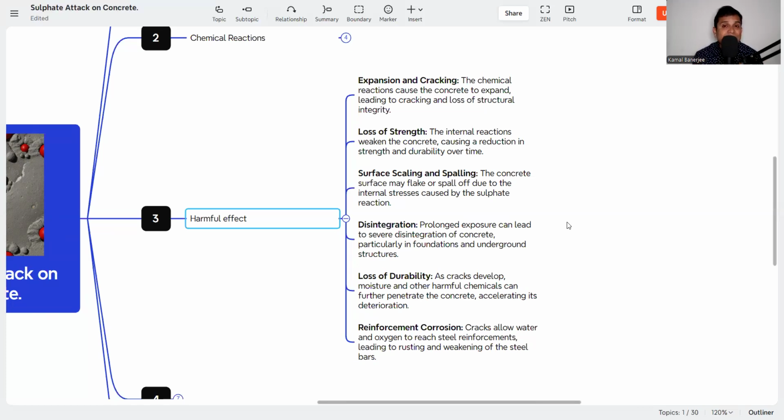cracks are generated. That means the concrete is not as per our requirement, and whenever a crack is there, it becomes a weak spot to penetrate more water, more chloride, more sulfate, more other ions, and carbon dioxide, which is also a problem for the concrete. So it is a durability concern, and structural stability is a problem.